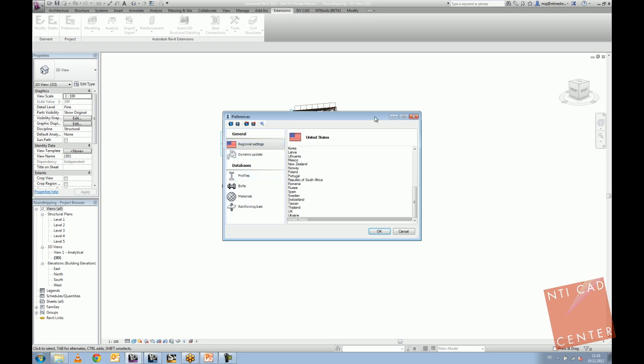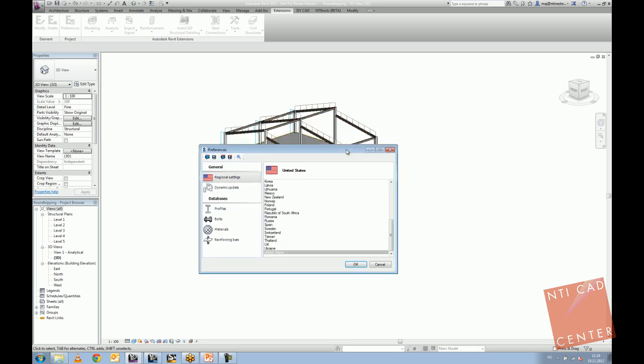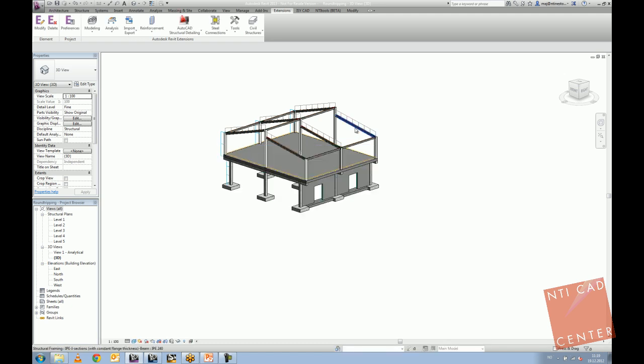So again, it might be an issue with profile mapping. What happens if you don't have a profile actually here? During this integration, you will have a pop-up window where you need to say, okay, this section was not recognized. What do you want to use instead? So you have section mapping possibilities. And again, you can do some manual mapping if you want through the file.